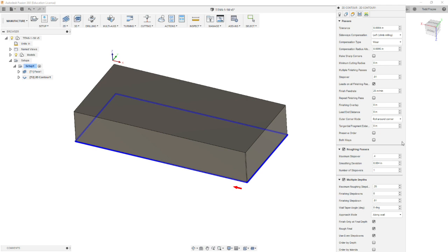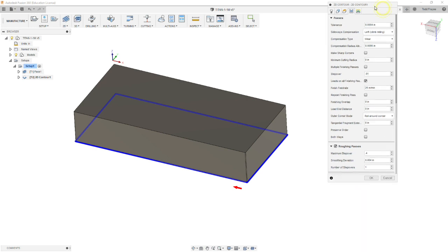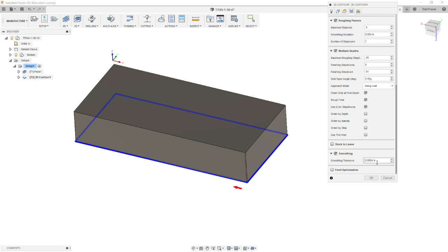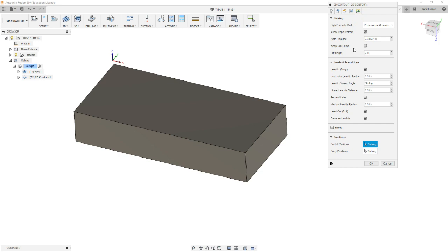Now the smoothing box, which I guess rolls you off the screen here, we're just going to leave at default at 4/10. So that smoothing is for the finish cut. It will only really come into play with the corners with this geometry, but its movements are going to average out so you don't get facets on your part. Okay. All right, going to the next tab, linking.